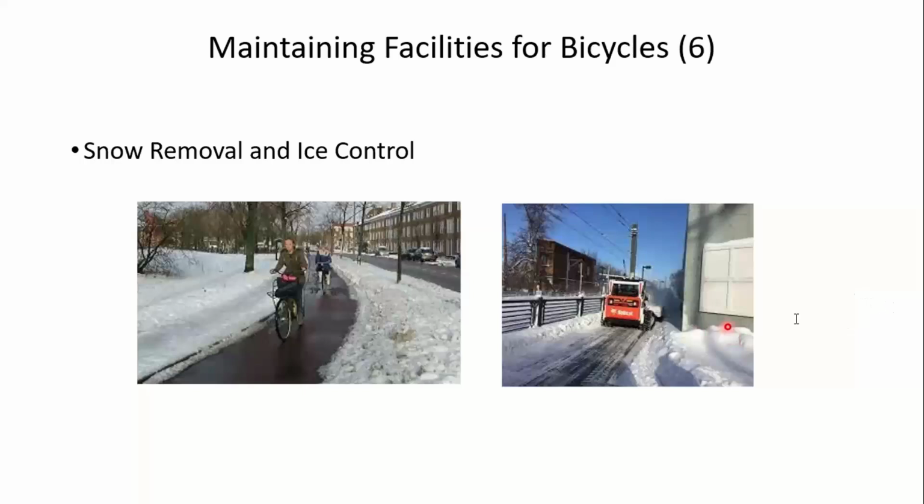And then we have a follow-up from Nicholas, or just the curb ramps. Yeah, just the curb ramps. As part of the resurfacing project, just the curb ramps need to be upgraded. But remember, any barriers or obstacles between the curb ramps, or in the middle of the block, those should be on your agency's transition plan to demonstrate that you're aware of those barriers. Good questions. Thanks, Ron.